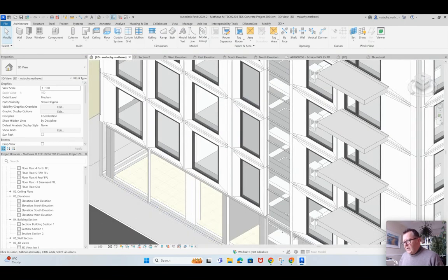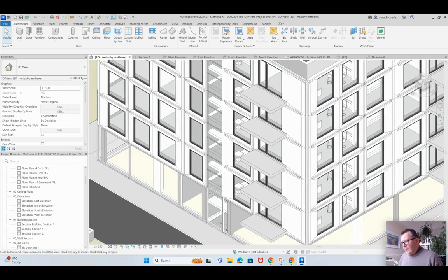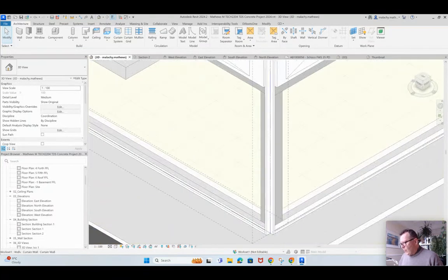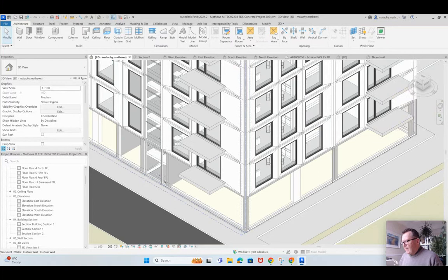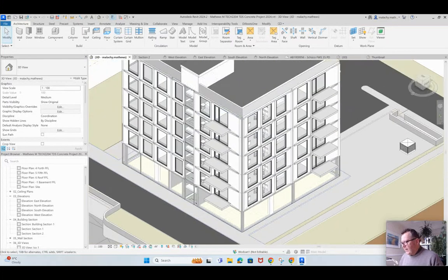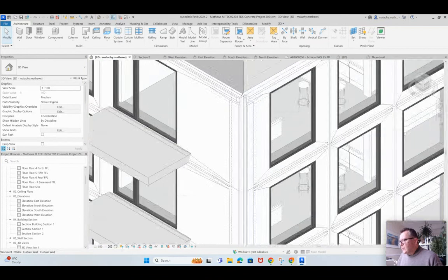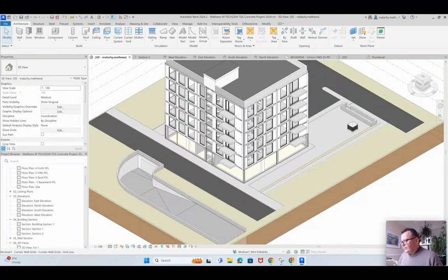I'm going to take a look at the south elevation here now, and you'll notice as well that I use that 50 by 1 is to 50 at the edges, so at the bottom, at the top, and at the edges of all of my 4 curtain walls around the building, and these actually run the whole way up here. Now, I'm not saying that that is a solution to where one panel meets the other panel at the corner, but I'm just going to do that for the moment. I'm just going to leave it there now.